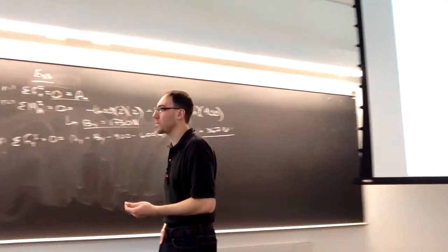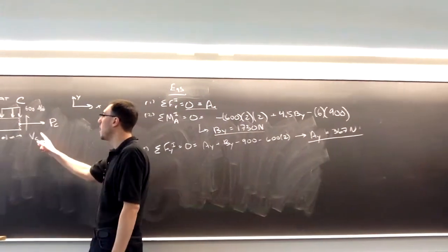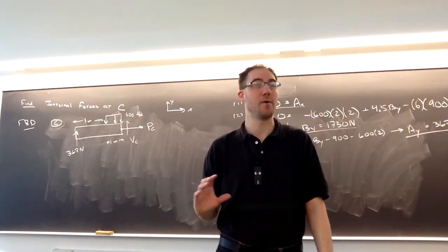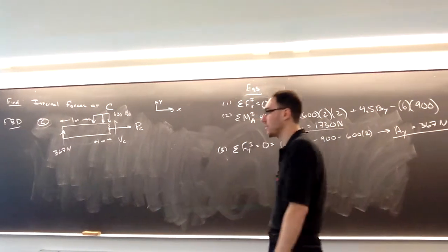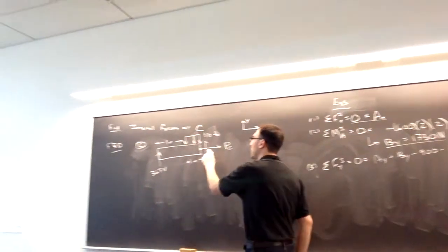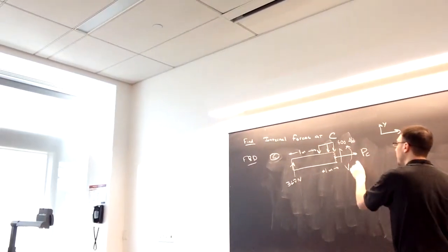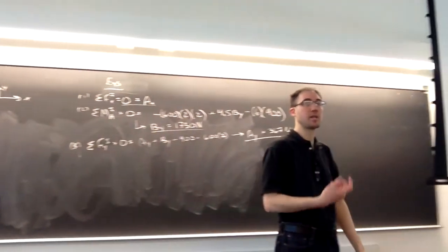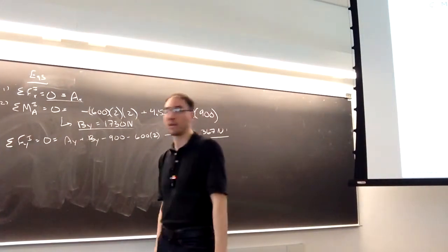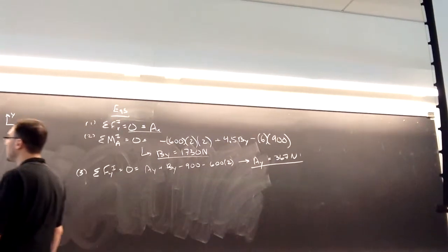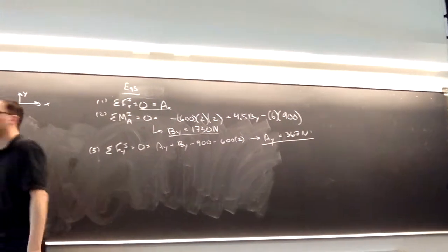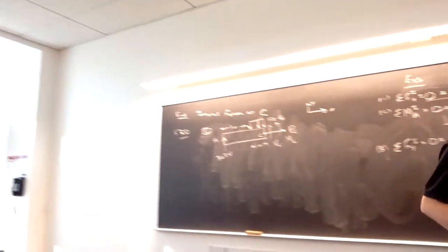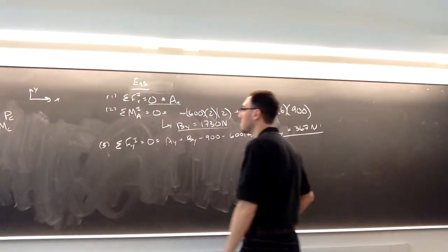Once we get further into the course and look at beam bending and combined loading, our assumption of direction will become more important. Here, if you say it's up or down, for the time being, it doesn't really matter, as long as you're consistent with your picture. Same thing with the internal moment. I'm going to assume it's a positive internal moment. But once we get to beam bending and combined loading, it becomes crucial to make the correct assumption of direction. Three new unknowns are introduced now, since we're in 2 dimensions and we cut through C.